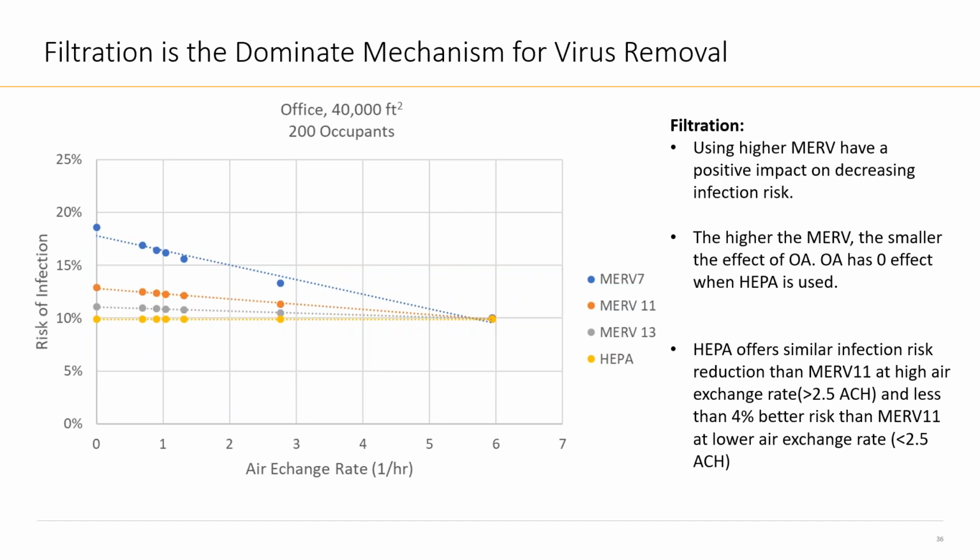So in principle, you don't need the demand control ventilation. You can just go through the IAQP and design for your pollutants in the building. So this will be my recommendation. You can always combine multiple strategies and use them at different times. You can always do that.